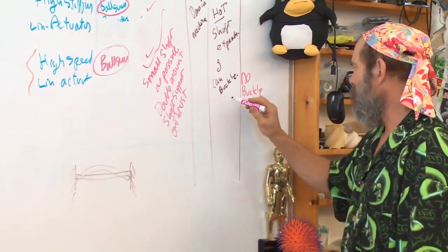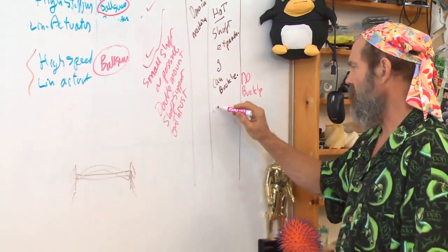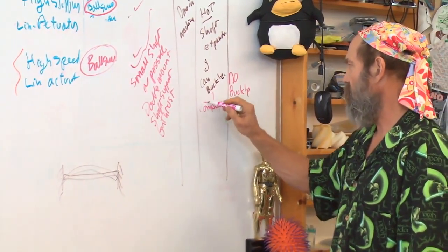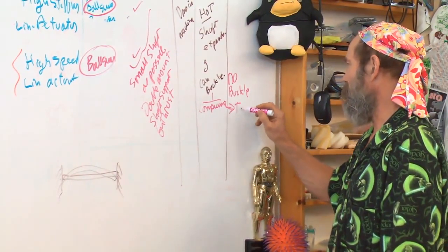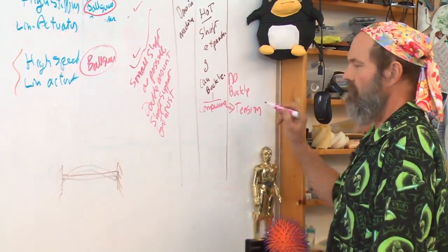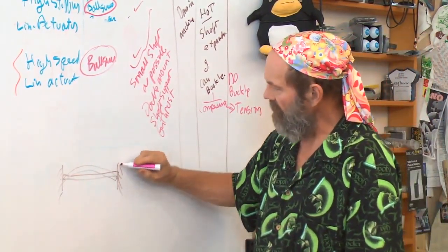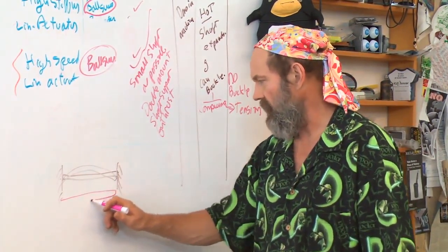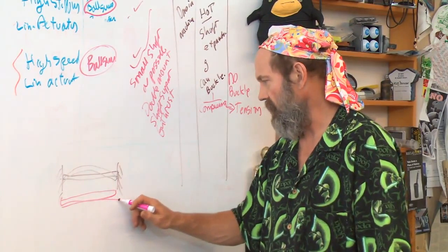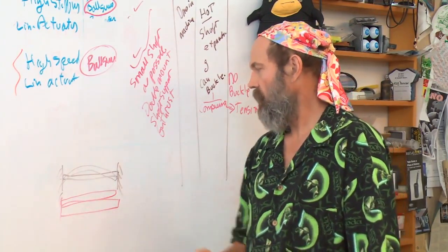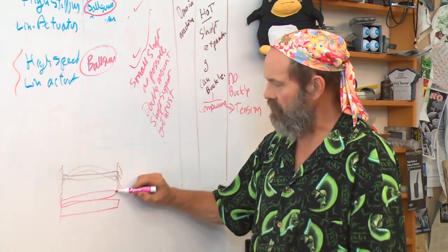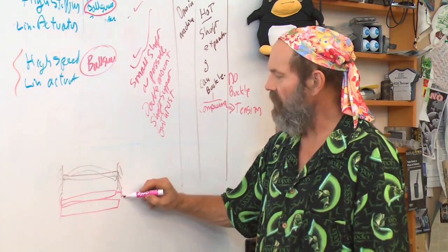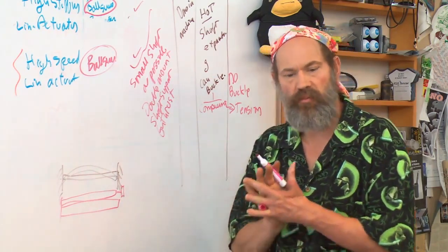No buckle. So what's the mechanism of buckling? It's essentially compression. I don't want it to buckle. What's 1 over compression? That leads to tension. Tension. So if I know that the change in length of the screw shaft is going to go from here to, say, here, why can't I initially mount the screw shaft in bearings and pull it, in other words, pre-tension it or preload it?